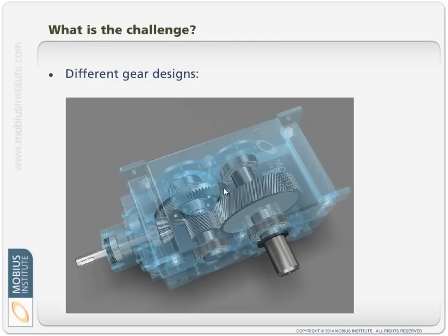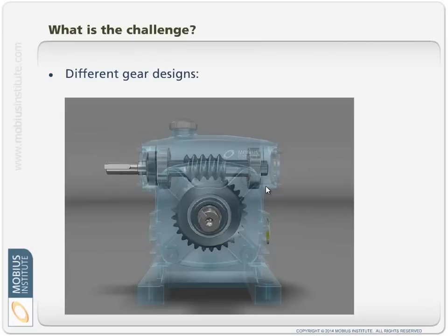Some people actually use the potential of resonance to help them, because they figure, well, if the case resonates, that's going to amplify vibration. That's an interesting approach, as long as you've got good repeatability and a good transmission path from these forces through to the point where you take the measurements. But as I say, good repeatability, then you should be in good shape. As I say, gears come in different designs, and you need to make sure that you're aware of exactly what you're dealing with, and not just treat it as a generic gearbox without knowing what's going on.